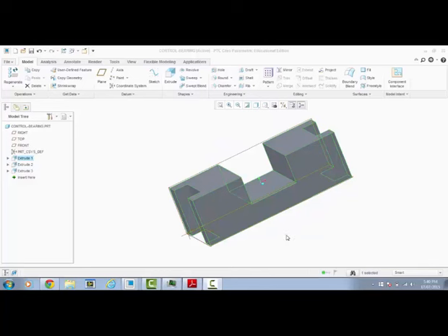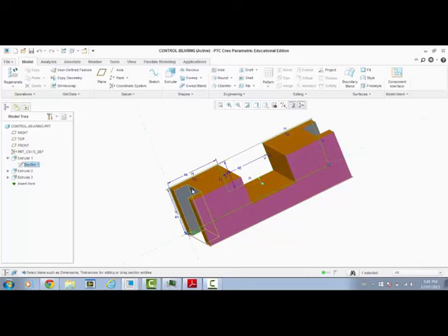I'm going to explain how to modify this object. If we want to change the height of the object from 41.5 to 60 millimeters, we have to look at using the model tree on the side. And now I'll explain how this works. The first extrude part, if we click on it with the left mouse button, it comes up as section. Click with the right button, and now we can change the dimensions. The dimensions come up. All we have to do is touch that dimension and we can change it.